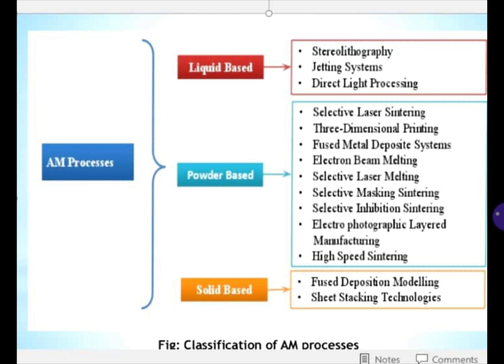In order to deposit a material onto the platform, we are either going to take liquid based material, or powder based material, or solid based material. So based upon the material type, whether the material is in liquid condition, powder condition, or solid, depending upon that we are going to classify the AM process.